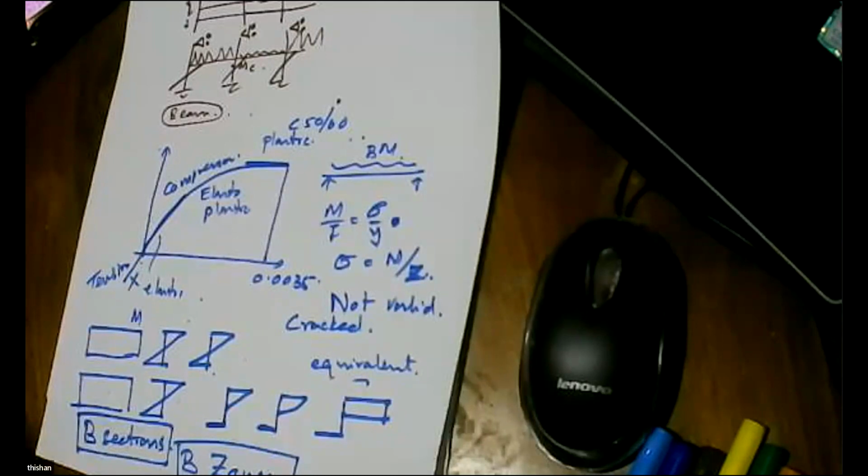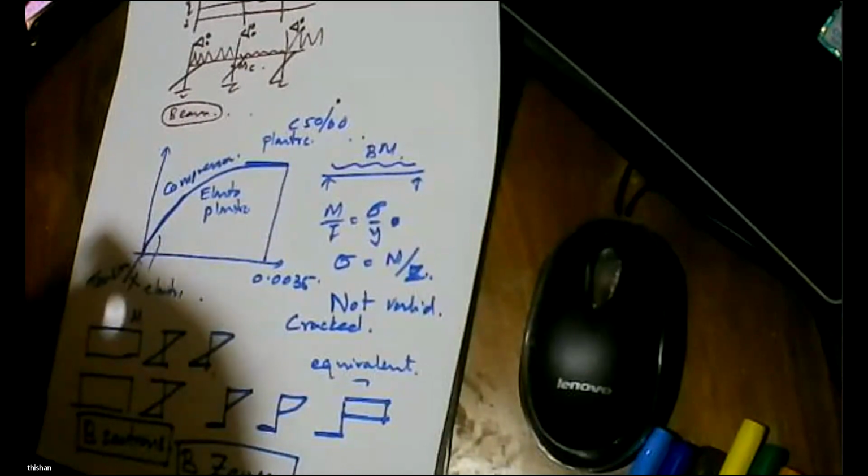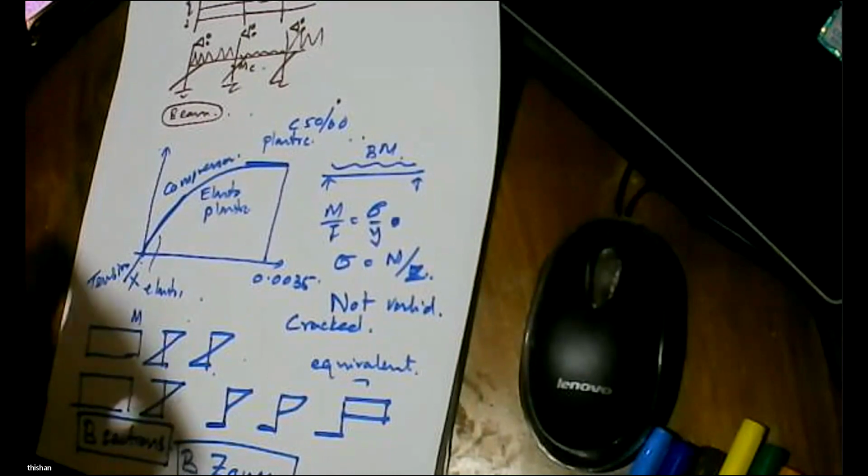The moment you develop bond, it can be as high as 400 or 600 kilonewtons per meter square under service conditions. If you get that type of very high value as the skin friction, and if we socket long, even though the rock is fractured vertically, the confinement is very high, and we will not have any problem.